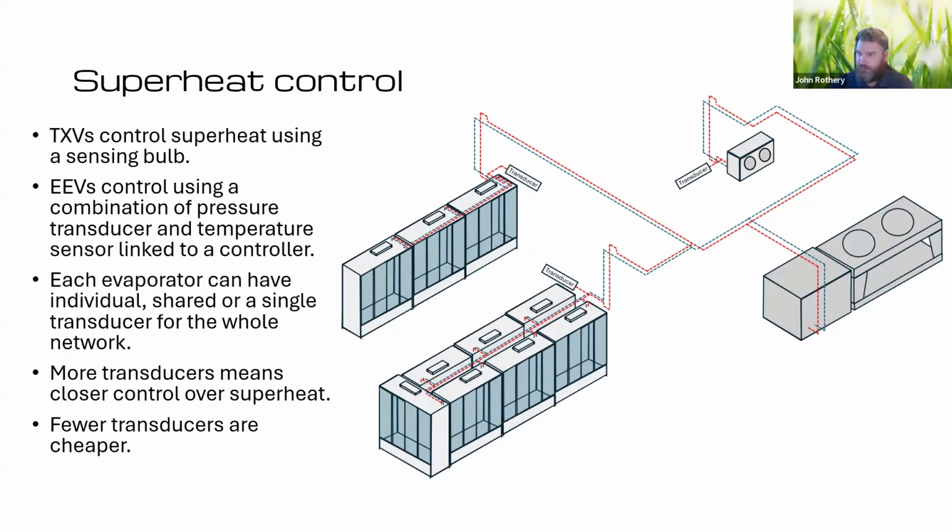Yeah. So you've got the manual fallback, and also you've got the transducer fallback, haven't you? If the transducer fails, you set it to, say, 20 bar. The transducer's off, but you still see that reading on your controller, so it sort of hides the issue. If you've got multiple transducers, you can compare one case to another, and it's pretty apparent that it's not moving and it's just flatlined on your graphs.